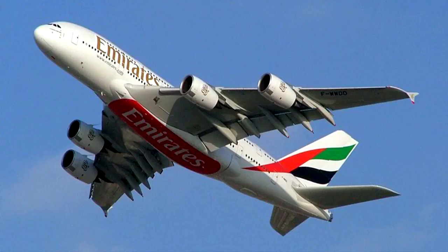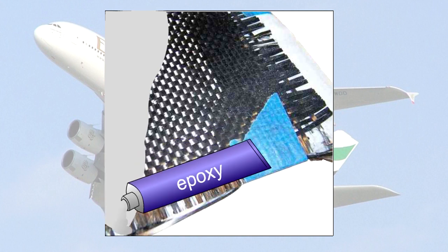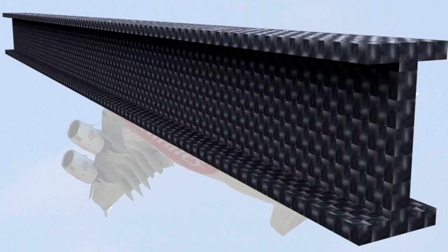Composite materials are becoming more and more used in aircraft construction. They are made up from layers of fiber, carbon, glass or Kevlar, molded into the required shape with a hot plastic resin, which is normally epoxy. Carbon fiber reinforced plastic is used where structural strength is required. It can be produced with the same strength as an aluminium alloy, but with a weight saving of about 20%.